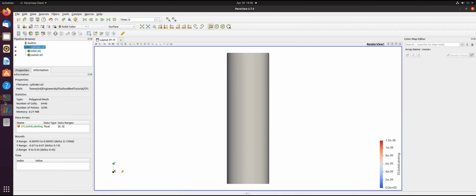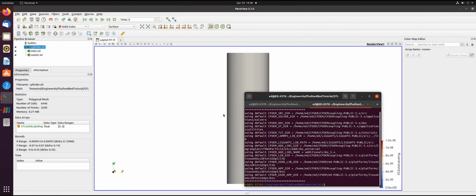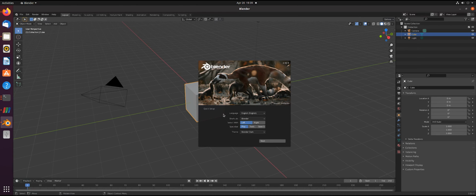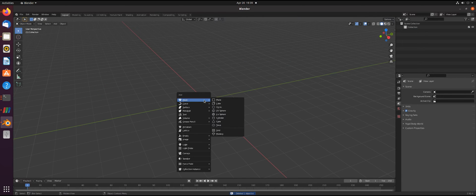If you have only simple structures, you won't need an expensive CAD system, but you can use Blender. It is very capable in modeling, but with the downside that it works a bit differently, and you will not have the possibility to use measurements and parametric modeling like in a real CAD system. I linked my Blender installation so I can open it with the command blender in a terminal shell. To do so, I make a new tab with Shift-Alt-T and type in blender.